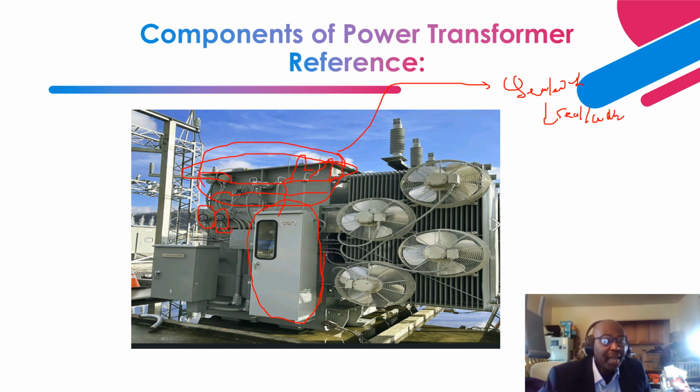Then over here are other auxiliary devices. As you can see, this is basically an example. I'm pretty sure this one is the top oil thermocouple that goes in on top, and it comes in here to the control cabinet before it goes to the gate. So this is a typical example of how the wiring configuration of the auxiliary devices looks like. Next is our stage cooling fans.